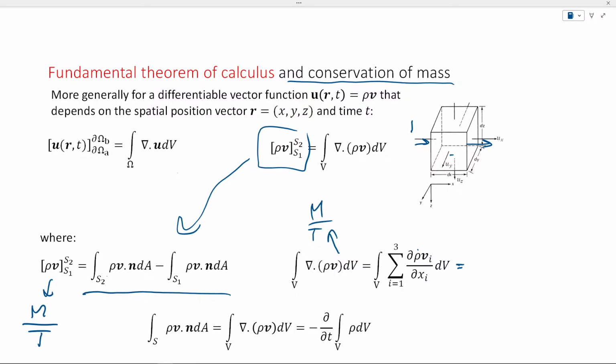So if 10 is entering here and 12 is leaving here, what is changing across my boundary is -2. So the net mass flux is, sorry, I have 10 units entering, so that's -2. The change inside my volume is -2 because I have 10 units entering and 12 units leaving. So that's -2, and -2 is equal to -2.